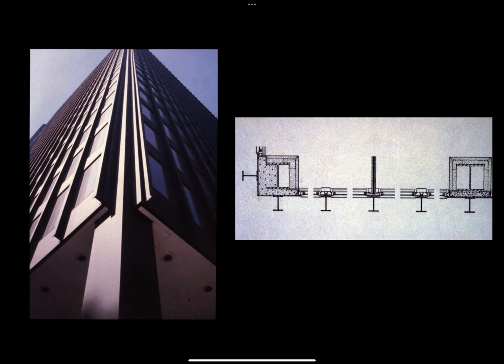On the outside of the steel section, they are encased in site-cast concrete, which is what you see in the photograph and also in the drawing. And then inside the building, that same column is encased with expanded metal and wet plaster. The little I sections that you see at the window mullions that go vertically up the face of the building are only stiffening the curtain wall glazing. They are not holding the building up, and therefore they do not have to be fire protected.